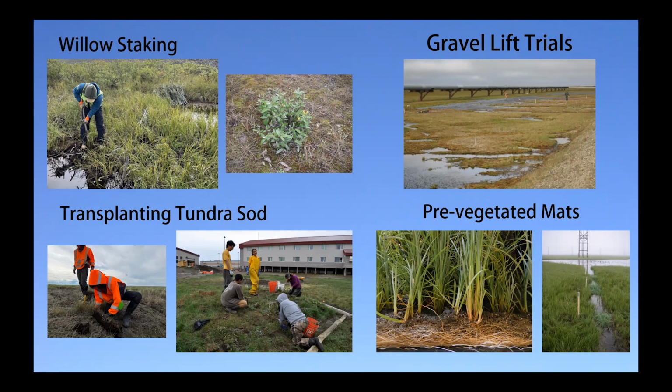So in my opinion, you should look at it from a landscape perspective, and in some conditions you can tell whether it's dry or wet, or it's an old drained lake basin. If you're going to have high ice volume, then you're going to want to remove less gravel, because you're going to have more subsidence, or in a drier area, remove more gravel because you're going to have less subsidence. And this piece of the puzzle has not yet been integrated into how things are performed. The gravel trials are somewhat informative, basically removing it so that your result is as close to tundra grade as possible is the best, but you have to do this ice prediction to get it right.